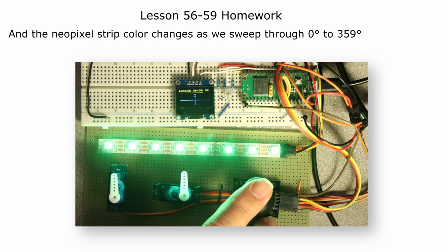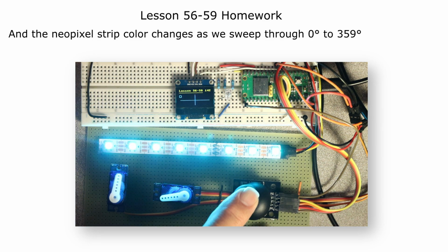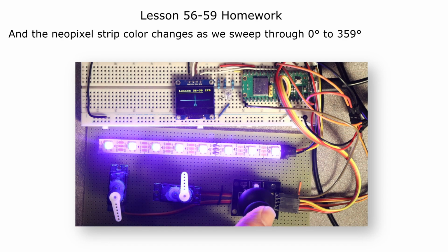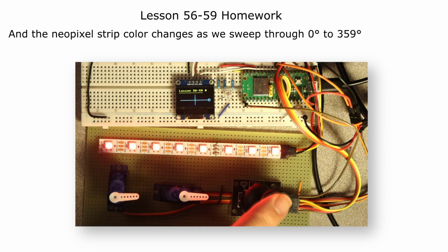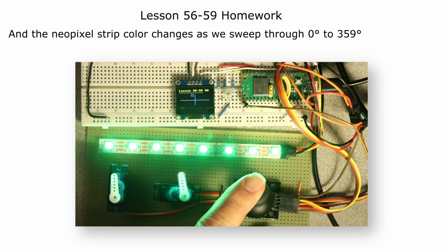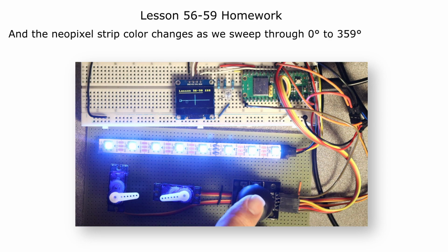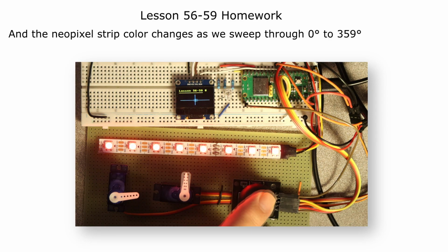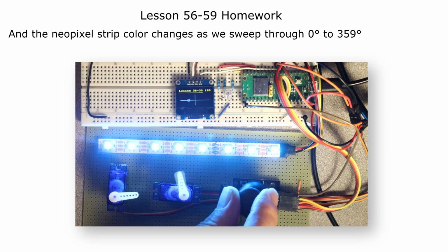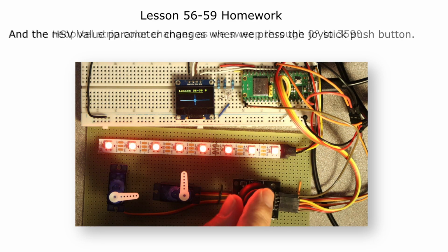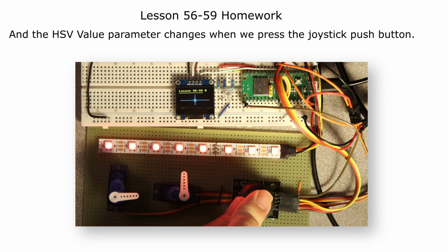And the NeoPixel strip color changes as we sweep through 0 to 359 degrees. And the HSV value parameter changes when we press the joystick push button.